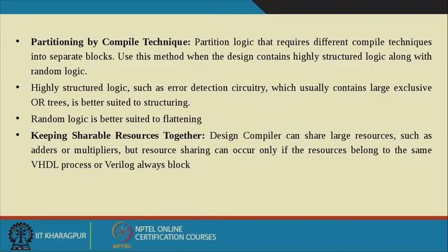Partitioning by compile technique says that we partition logic that requires different compile techniques into separate blocks. Use this method when the design contains highly structured logic along with random logic. Random logic is better suited for a flattened design, and highly structured logic such as error detection circuitry, which usually contains large exclusive OR trees, is better suited for structuring. So different blocks need different partition strategies.